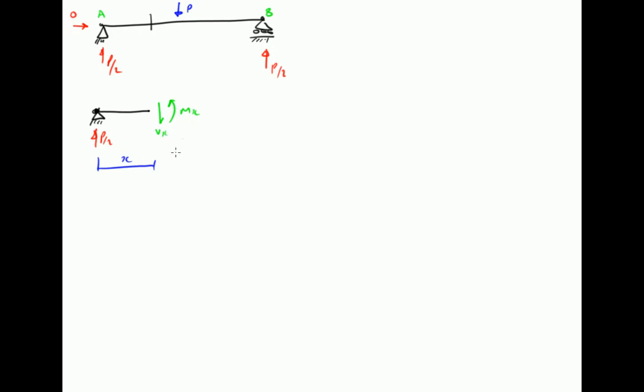So the moment, Mx, this time we're looking at the moments. Again, from our third equation of static equilibrium, we established that the sum of the moments about the z-axis at some point on the plane have got to equal 0. So we have bending moments due to, at this section, a P divided by 2, multiplied by X, the distance along, and that has to be counterbalanced by, so they are acting in the clockwise direction, and we then have a minus Mx, which is this internal bending moment within the beam, which has got to equal 0.